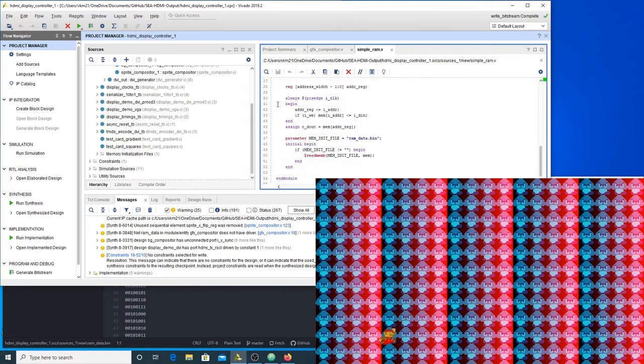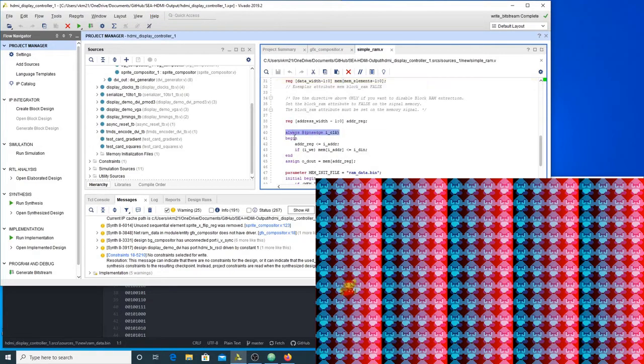And then you have the simple clock functionality, right? To say, okay, whenever the clock is at the positive edge, collect the address register so that you can read data from it. And by the way, if you actually have a write enable signal, then we're going to set that memory address to the data that we're receiving as an input. And no matter what, every clock cycle, we're also just constantly making sure that our data out is equal to the memory that's at that address register, which gets set here. So pretty straightforward, very, very simple, but really essentially defining what a RAM is.